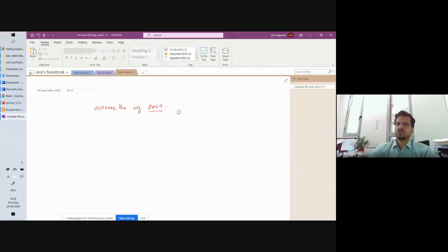Initially, everything is zero. Zero strain is there. Then you start increasing to, let's say, epsilon 1. For epsilon 1, you calculate the total strain in each fiber. Each fiber had a particular level of strain value, right?